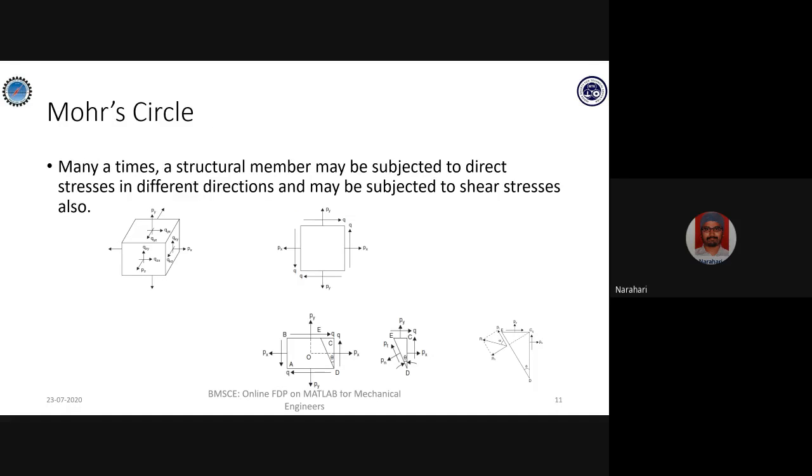Okay, so let's quickly also have a look at Mohr's circle. Before we go to Mohr's circle, we need to know what compound stresses are. Basically, when any body is subjected to a multitude of stresses in different directions, we call the stresses induced within the member compound stresses. Generally, the universally applicable thing is a three-dimensional stress element, or a stress tensor element, which is seen on the left hand side.